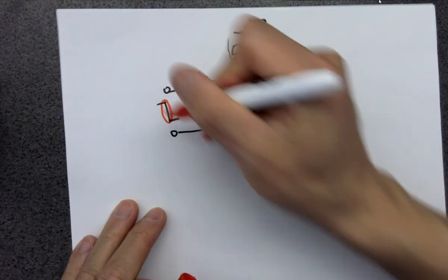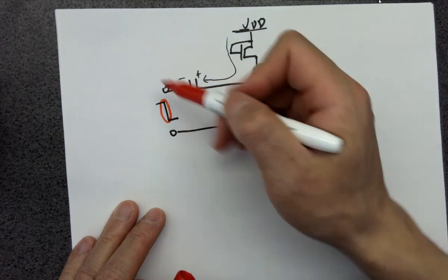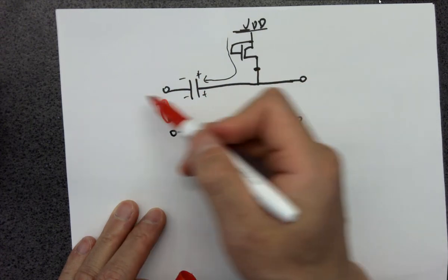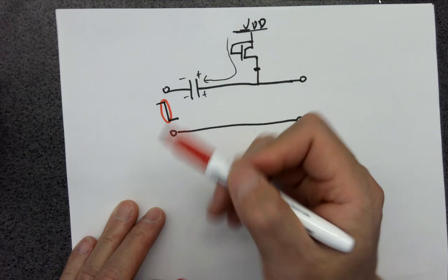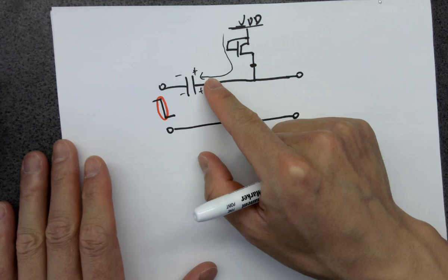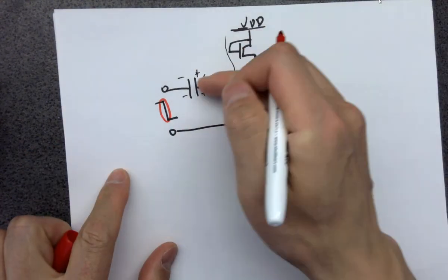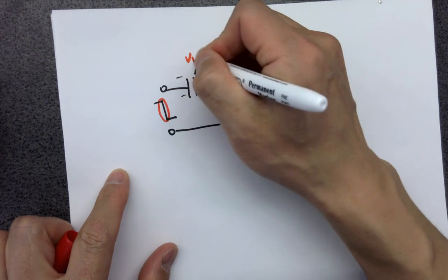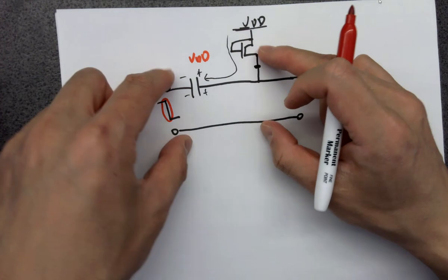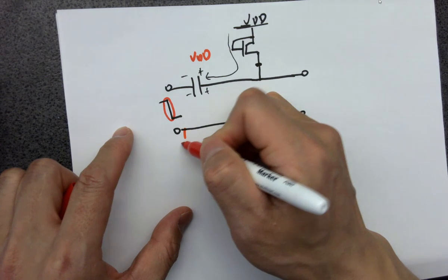Only happening here. Whenever it reaches the DC voltage, steady state, the DC voltage is not changing anymore. However, during the ramp, whenever it's pulling, it's an AC signal, it's going to pass through that capacitor and dump charges to the cap. So when it's dumping charges to the cap, ideally the final voltage across the cap will be VDD, because it's trying to dump all the charges, or eventually form a voltage across the capacitor to be the same as VDD, because this point is grounded.